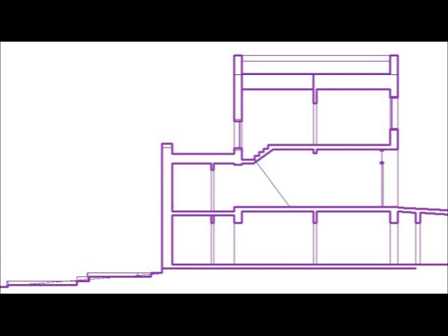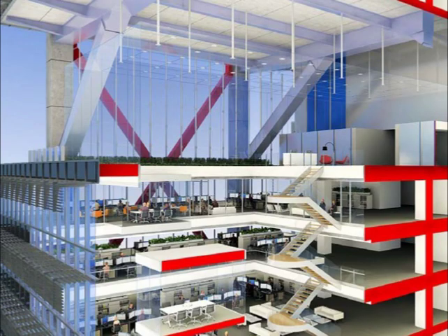A section drawing shows a view of a structure as though it had been sliced in half or cut along another imaginary plane. This can be useful as it gives a view through the spaces and surrounding structures, typically across a vertical plane, that can reveal the relationships between the different parts of the building that might not be apparent on plan drawings.